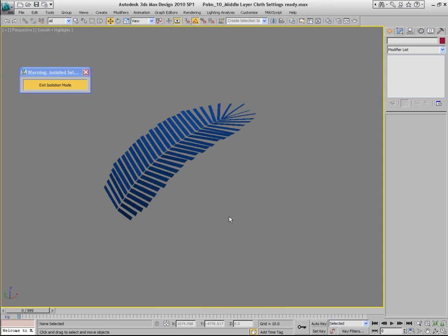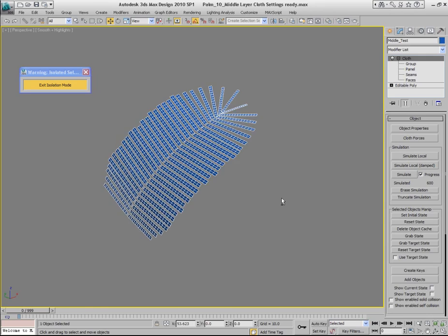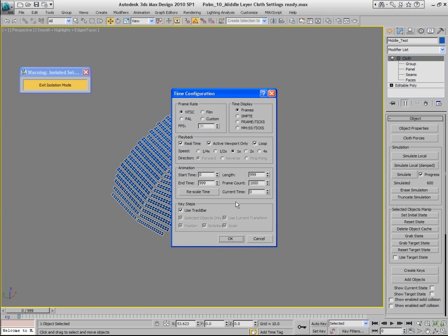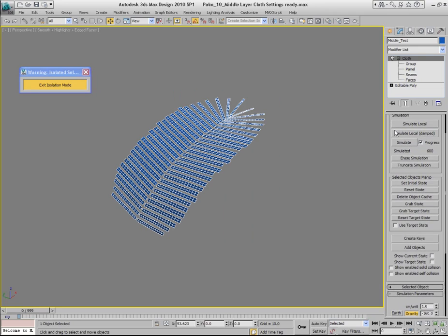And by the way, we are very close to the end, so it's going to take us maybe 5-10 more minutes to finish this exercise. So what you want to do is set the number of frames of your 3ds Max scene to something larger than 100, which is what you have by default. I set it to 1000, or you can set it to even 2000, and then you click the Simulate button, and it's gonna calculate the simulation, but it's gonna keep it for every individual frame.